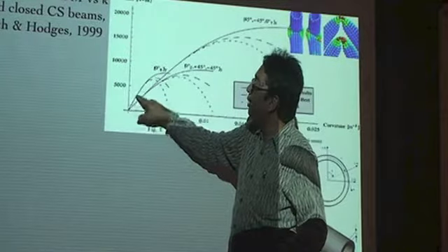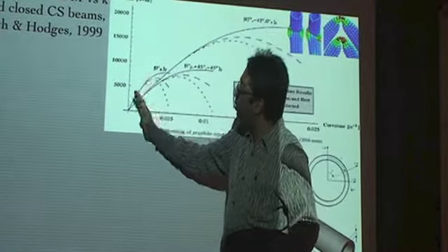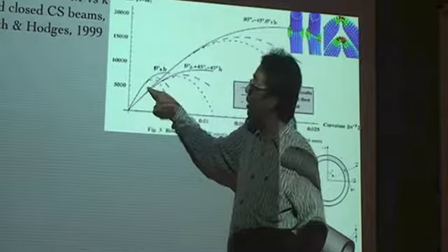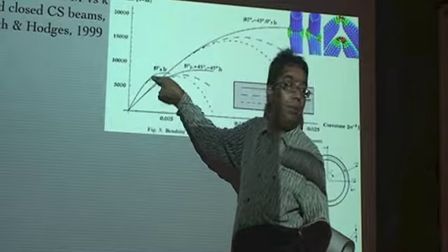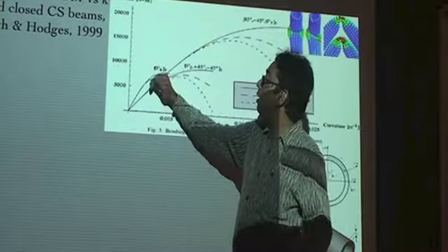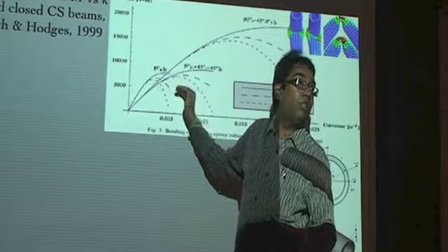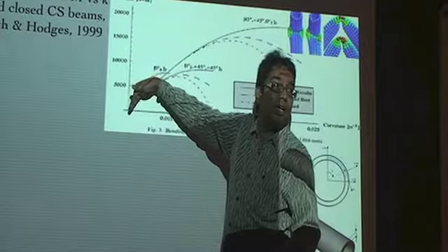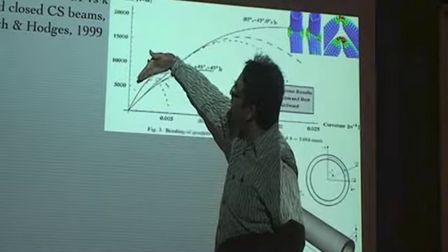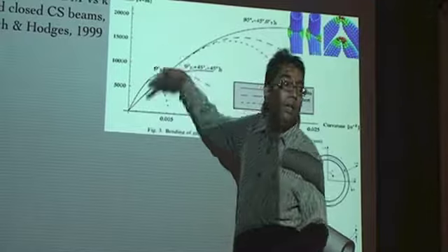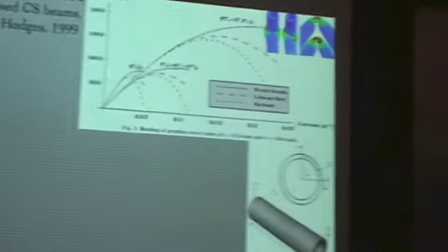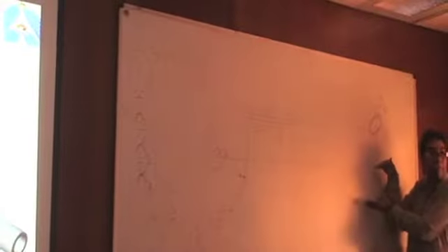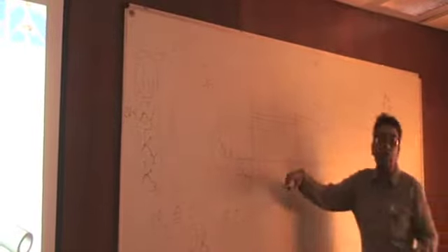But then as you increase the bending load, it will be almost linear up to a certain extent, and then it basically bends downwards. In other words, your curvature increases much more rapidly. Okay, so the slope of this is your EI2. So what is happening as you come here is your EI2 is reducing because of this flattening which is happening, because of which your I2 is basically reducing. So when your I2 reduces, your EI2 reduces, and that's basically what is happening.